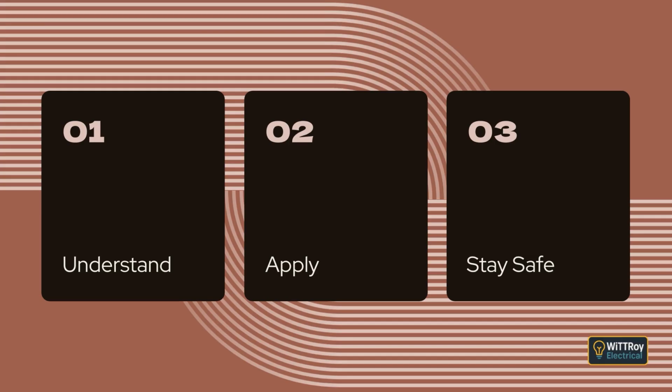A socket outlet must not be used as an emergency switch, unless the equipment is supplied only through that socket and the switch on the socket acts as the emergency device.